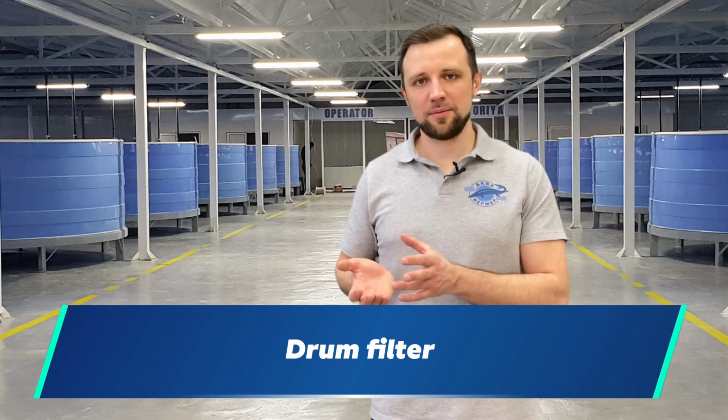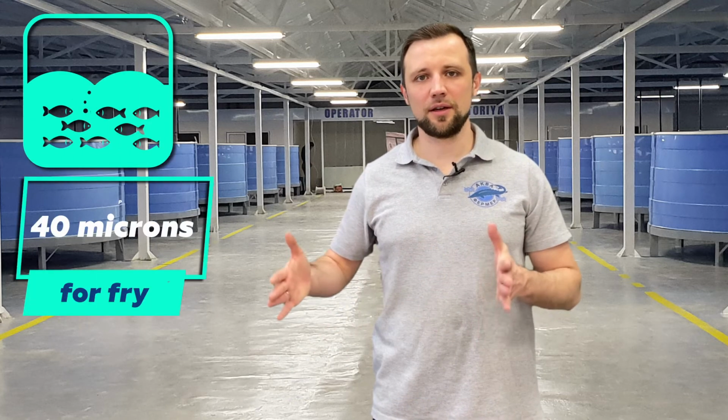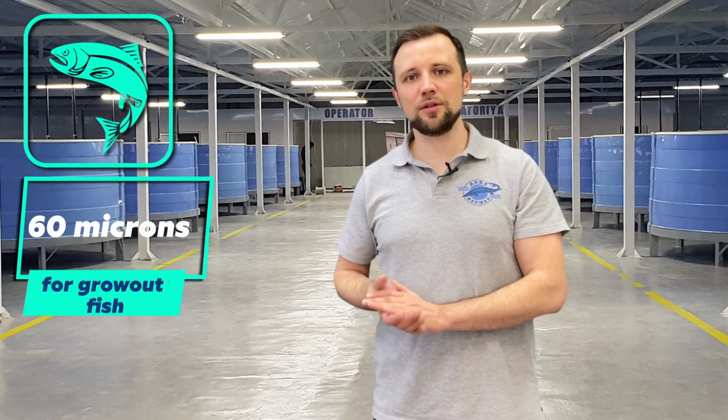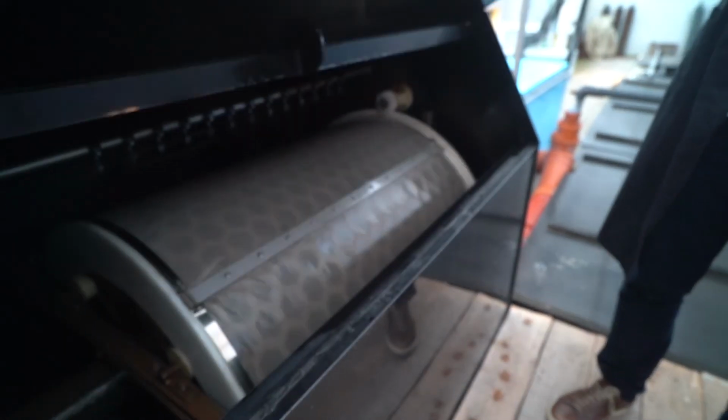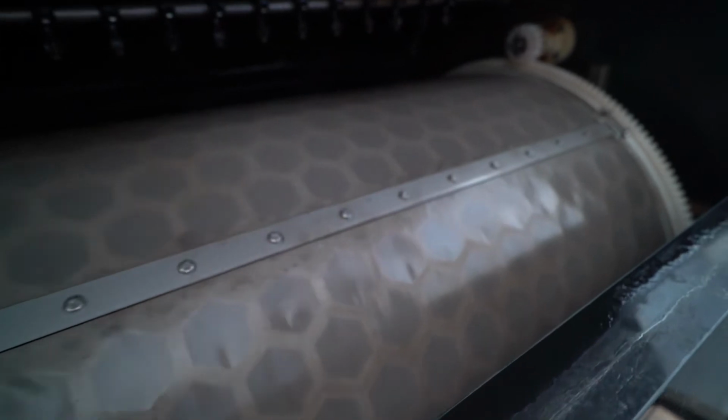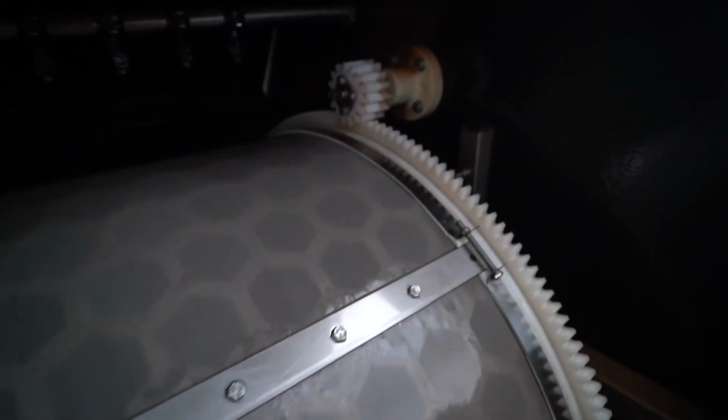Drum filter. Based on my practical experience, 40 micron mesh is recommended for fry, 60 micron for grow-out fish. Of course, some of you might insist that a 40 micron mesh should be used everywhere. Others will say 60 everywhere. Someone will probably have a different opinion, but it's normal. We all have different approaches.